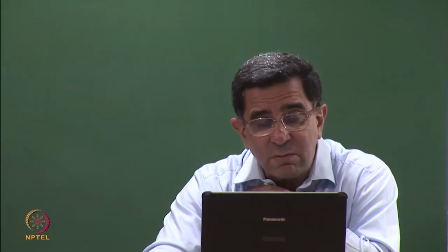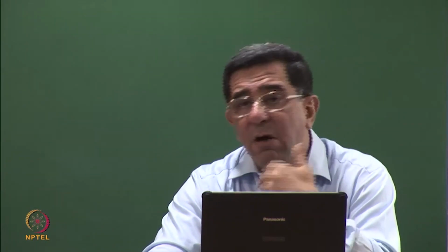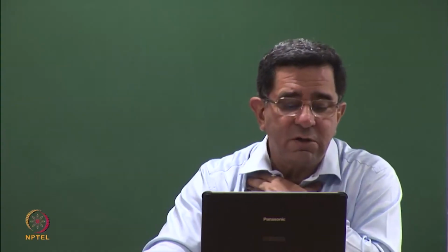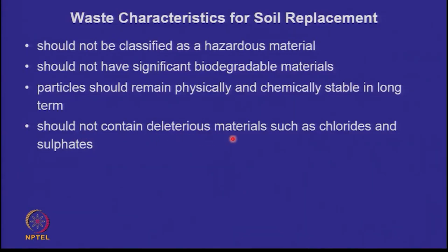If you have limestone in a protected environment, it will work, but on a long term basis where there are going to be spills of acids, or there may be an acidified environment, you may have an issue. Even in natural limestone formations, geologically you find some seepage channels which have dissolved over a geological time frame. So, particles should remain physically and chemically stable, should not contain deleterious material.